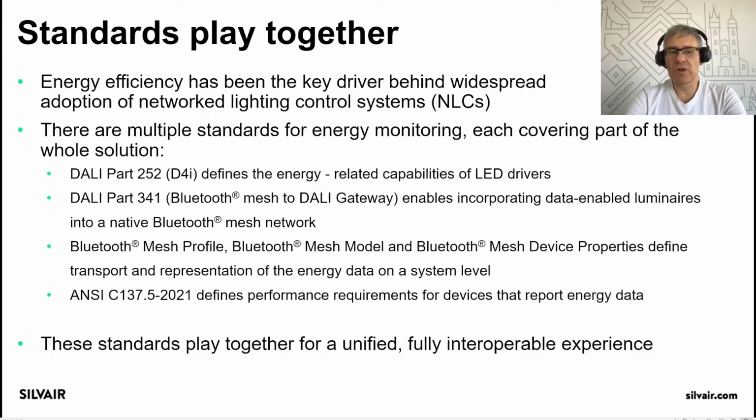So the first one we'll cover is the DALI part 252, which defines energy-related capabilities of LED drivers. Then we have DALI part 341, which defines the translation between DALI data and Bluetooth mesh data. And then last but not least is the ANSI C137.5, which defines performance requirements for devices reporting energy data. As I said, the standards play nicely together for a unified, fully interoperable experience.